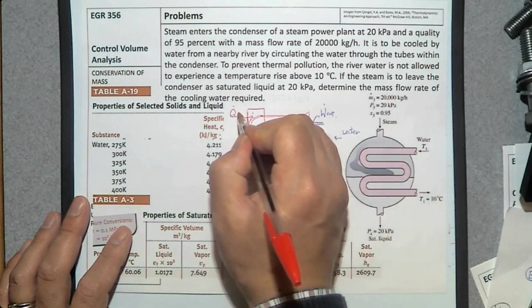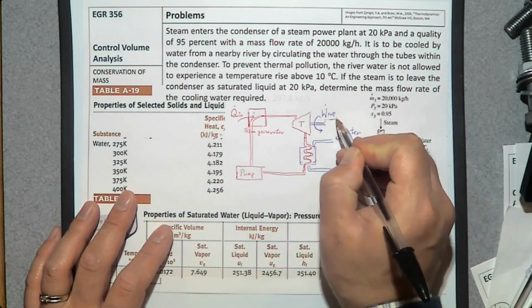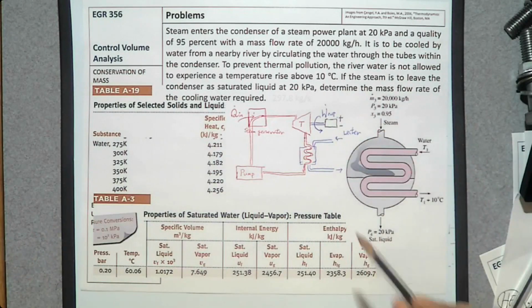So here we have the rate of heat transfer Q in. We heat this steam to increase the pressure and temperature. Then it goes to a turbine and expands. During the expansion of this steam, we can produce mechanical power that is going to run a generator. So that's how we produce electricity.